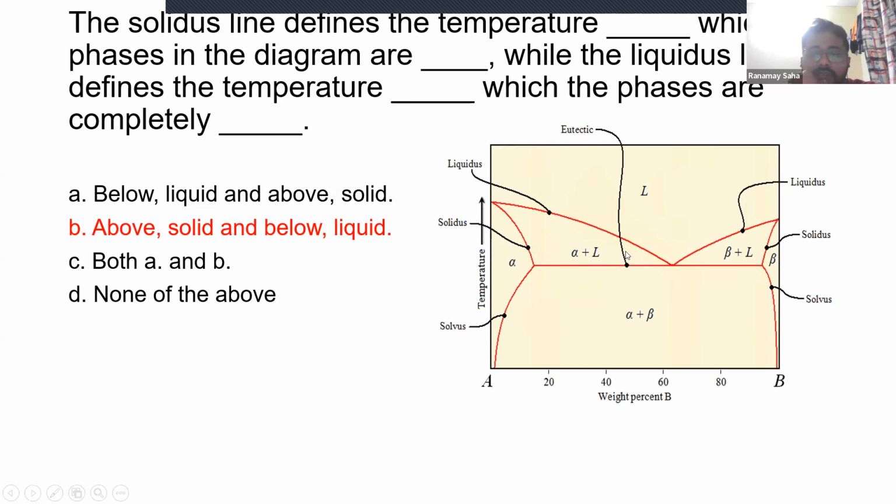These lines are called liquidus lines, the line differentiating the pure liquid from a mixed solid-liquid phase. Solidus lines are these ones which differentiate the pure solid and the solid-liquid phase. And solvus lines differentiate two solids, both solids, but having different microstructures. Like here we have alpha ferrite and there we have alpha plus beta, maybe some different composition.